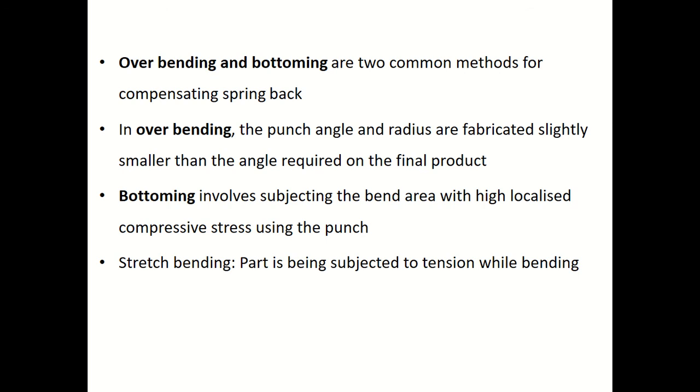So after the bending operation, you can ensure that the desired value has been obtained. Another important technique is the bottoming. Bottoming involves subjecting the bent area to highly localized compressive stress using a punch.